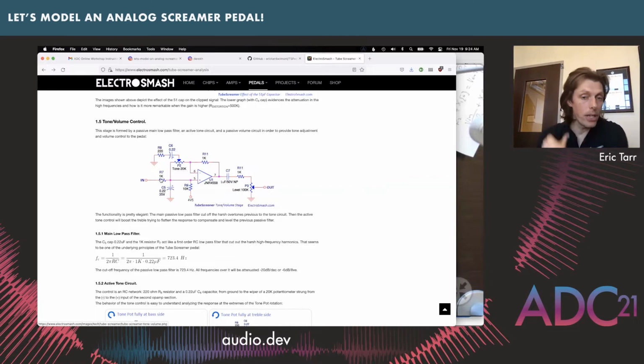So what you can see, I'll talk through some of these things, is we have resistors, capacitors, an op-amp, and potentiometers. Those are all components that we have discussed, and we have these different nodes that we can go through and label. We have our input voltage node over here. We have our output voltage node that's taken off of this potentiometer. We have this op-amp in the middle with a positive terminal and negative terminal. And we have ground. And then we have some other things that I need to explain how we're going to deal with in our model.